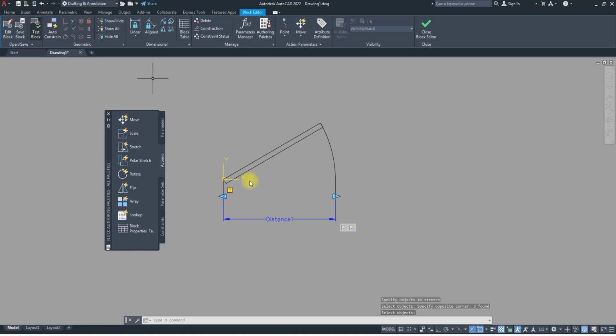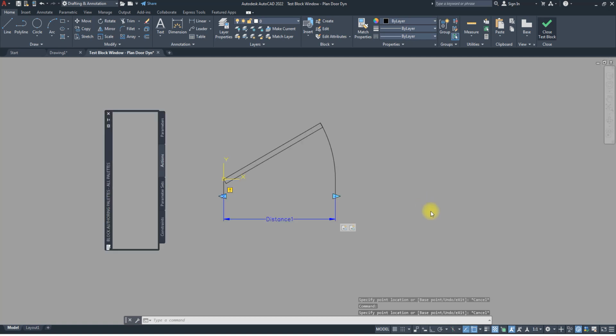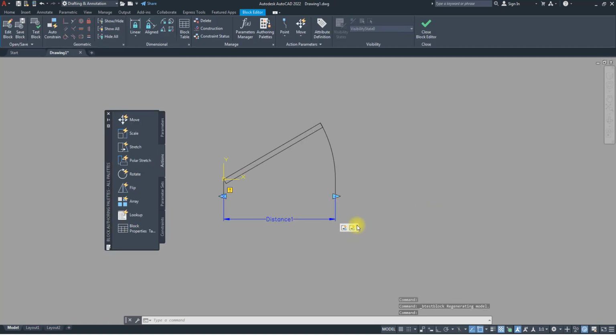So let's test this. If I click on this guy and I try to stretch, you notice what's happening. Are you noticing? So that means this one is not stretching anymore. So let's close. Let me right click. Let's delete this stretch. Let's start again. Sorry, my bad. Select this guy, then select this, and let's make our stretch over everything like this.